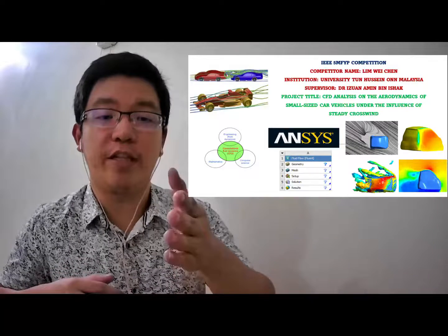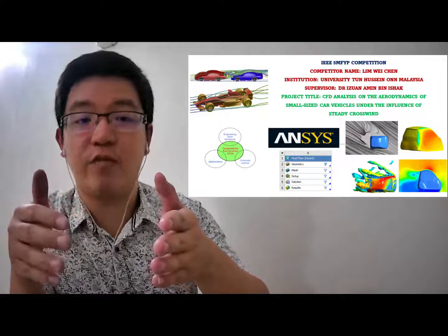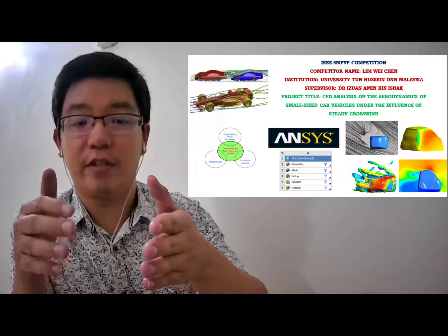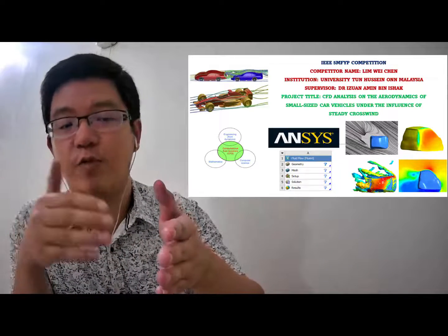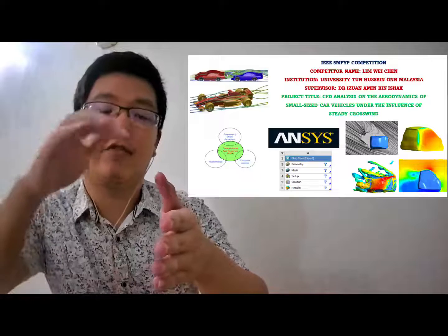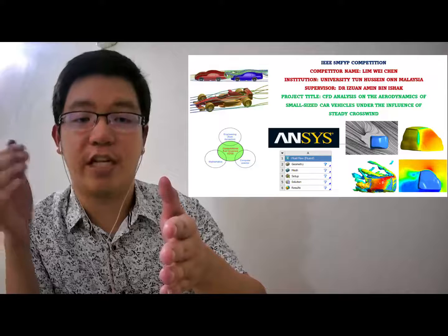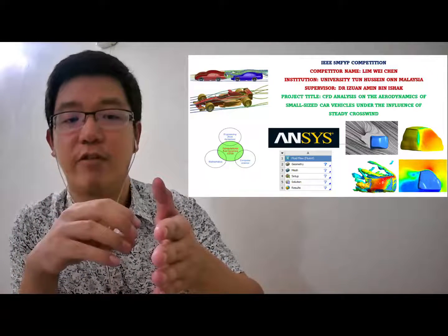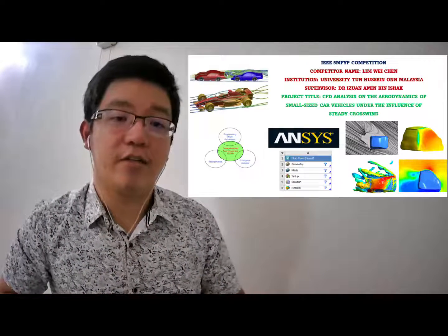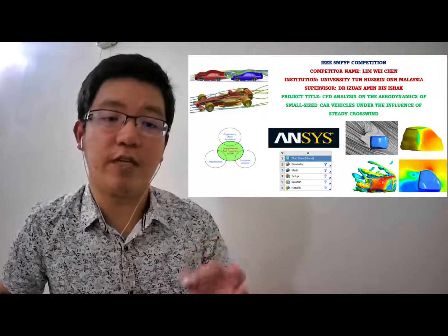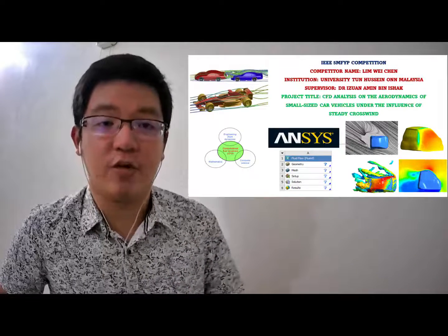Without the crosswind, just imagine a vehicle traveling on its path. The wind involved without the influence of crosswind is the headwind and the tailwind. The idea of crosswinds comes in where it will affect either the left side of the vehicle or the right side of the vehicle. For example, if the crosswind comes from the right side of the vehicle, when it hits the vehicle, eventually it will cause the vehicle to be deviated and it will cause the crosswind yaw angle. The minimum crosswind yaw angle is 0 degree, which is no crosswind, and the maximum is the 90-degree crosswind yaw angle.